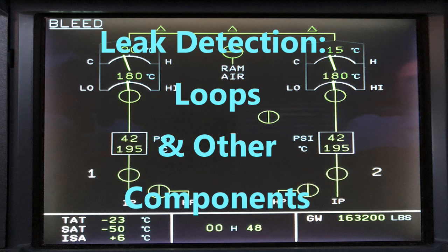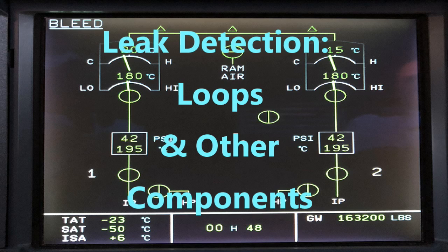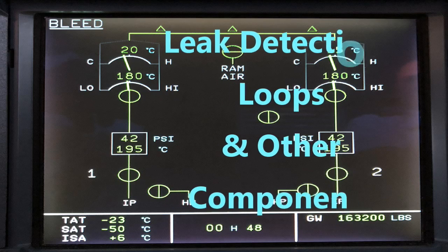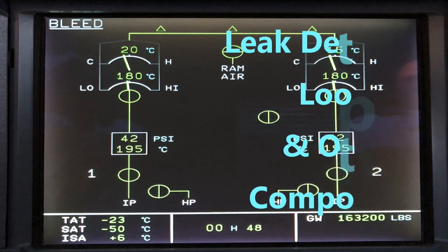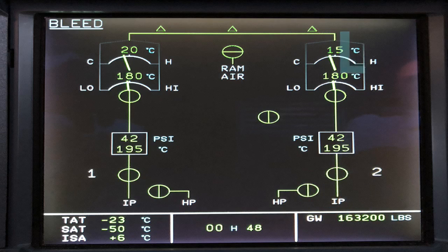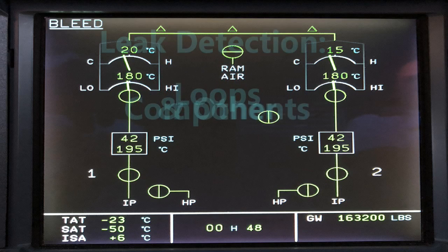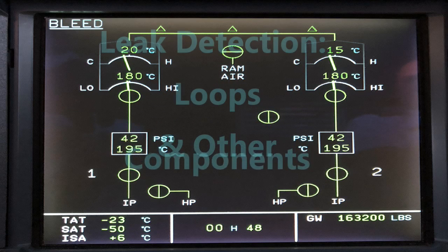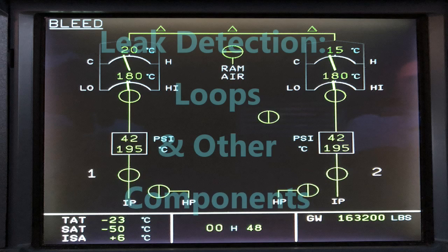But, and again, I know, but that's what this is. These are actual detection loops that make up the detection system, and there's 7 of them. Those monitors, those computers, are going to be monitoring those detection loops. You've got the detection loops running through the wings, so you can kind of see the diagram and where it's going. You have loops A and B. You've got your right hand wing, your left hand and right hand pylon loops, and fuselage APU loop.